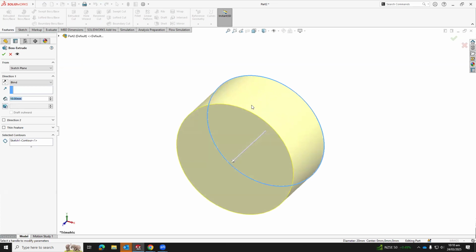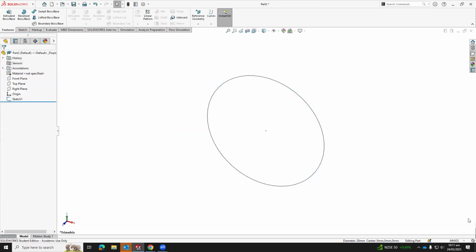Yes, Glenn? Can I please interrupt you quickly? So on my SolidWorks, the units for mine was inches. How would I convert that to millimeters? Okay, you come to this corner here, and then you change that from, for example, the IPS system to the millimeter system. Okay, Clint? Yeah, sweet. Got it.